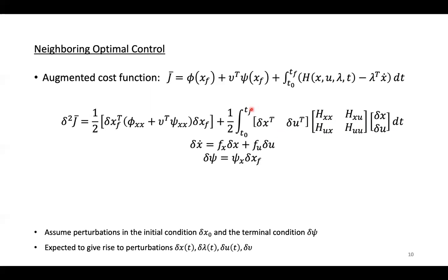But if you accept this form and you try to linearize the nonlinear dynamics about the nominal solution that you got, let's say from some controller, from some oracle, and you take the linearized form for even the terminal condition, you can solve this problem using the LQR format. And the solution will be of this form. So this is exactly minus R inverse B transpose lambda. And since you have the cross terms, you have to add this extra term, which you can derive using the stuff that we had discussed till now, but with slight modifications. And it shouldn't be a big deal.